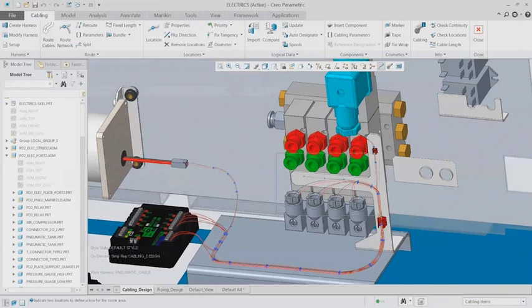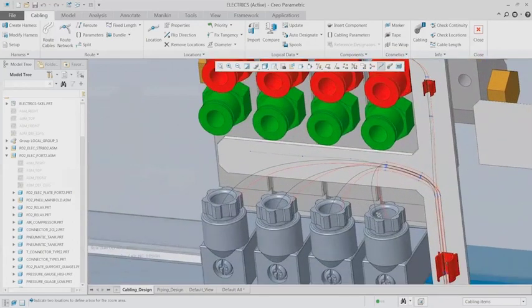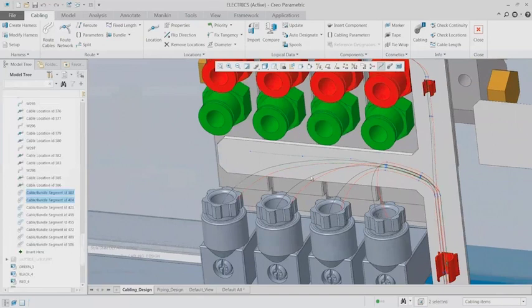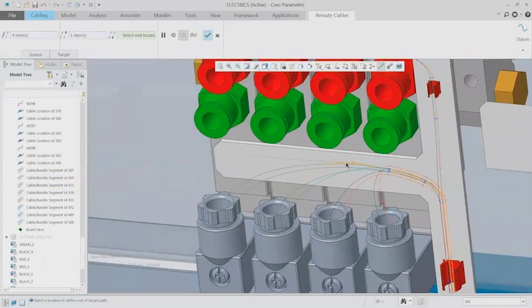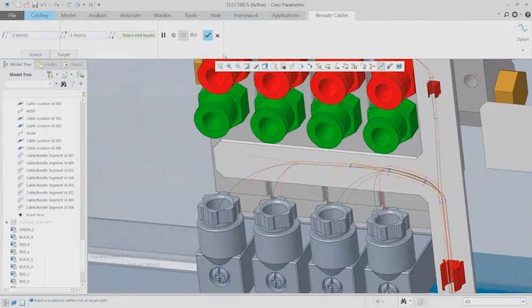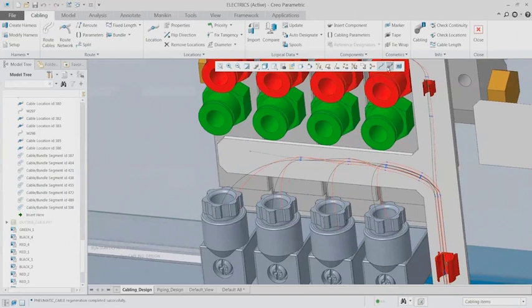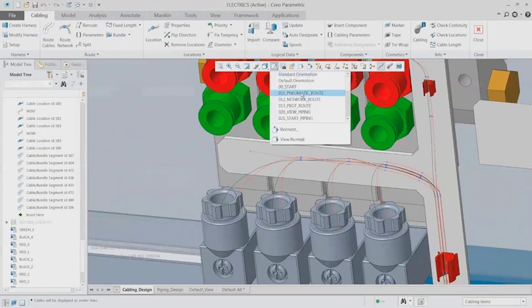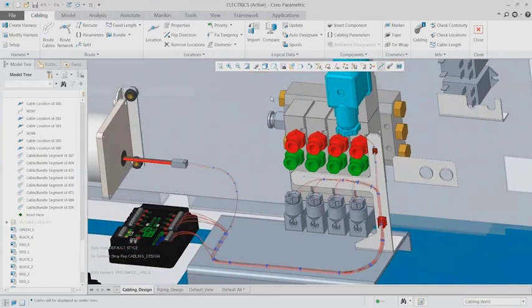Now, there are sometimes some issues as we do the routing. As you can see, some of these cables are going through the actual CAD model here. But that's not really a problem. As the designer, it's going to be my job to make sure that this model is fixed up anyway. So we can always go back and reroute these at any point. If I want to do a group route, make sure that they all get roughly to the same location, and then maybe go back and refine it a little bit and move exactly what points they're going to go to. I just need to move these a little bit further so they're not completely intersecting with the existing models that I have. But I can go through and clean those up at any point. You can also have it completely avoid going through a particular surface, a particular reference that I have. So there's a few ways to go through and route that.